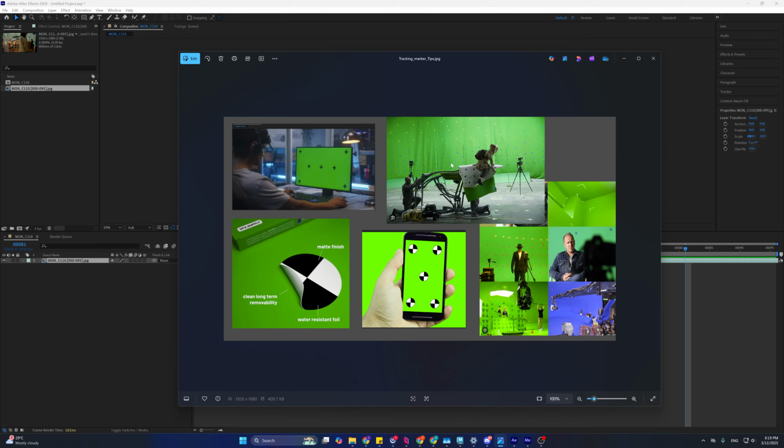So for example, if this is the distance from the camera, you have to make sure that the tracking point is big enough, because you can see from here we are looking at the screen, the tracking point is big enough. But if I move this tracking point to this position, you will see it's very small, it only appears as a dot here. So you should check every scene, camera and distance.